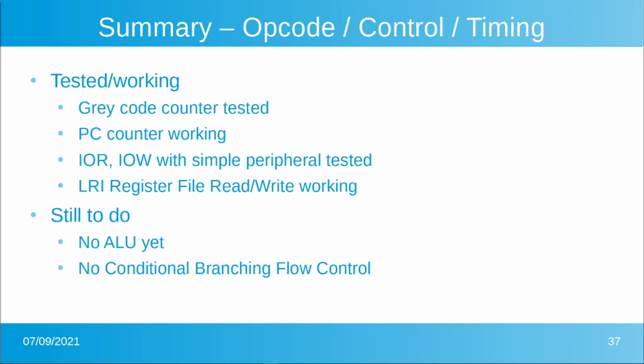I/O reads and writes worked with a simple peripheral. We're able to write to something, have that something complemented, and then read it back and see it coming back complemented. And we also know that the load register immediate, register file writes and reads are working. That's something we'd perhaps not verified as we should have.